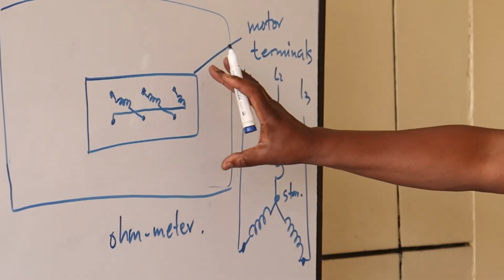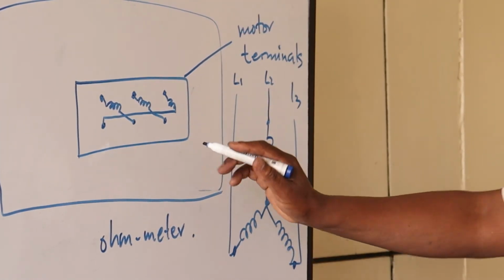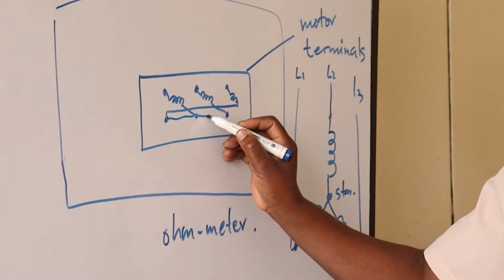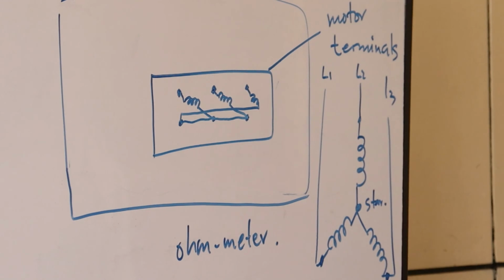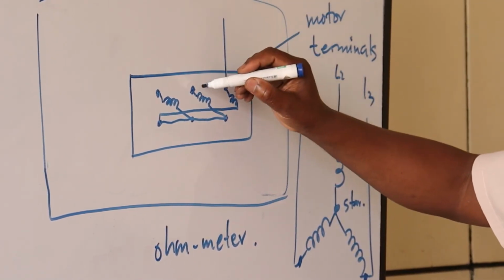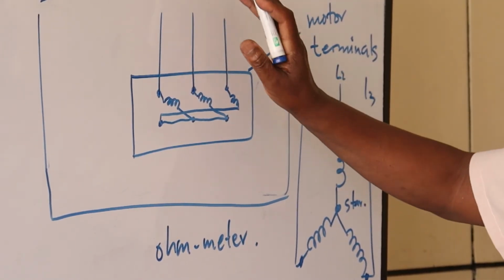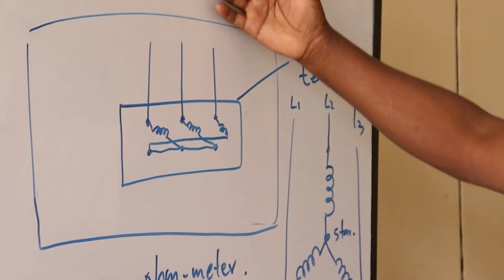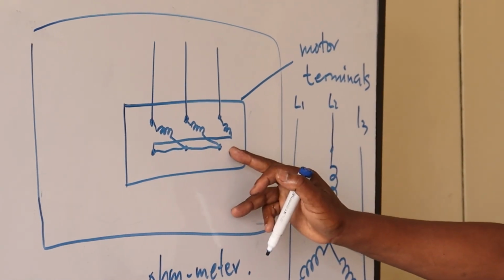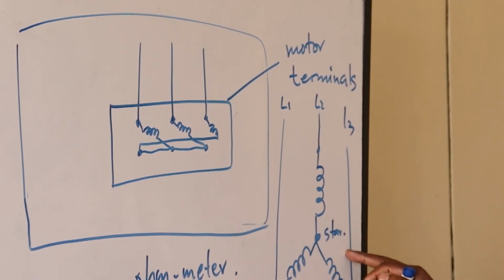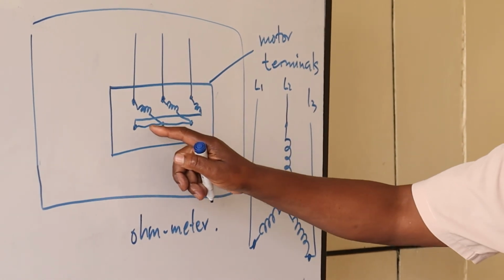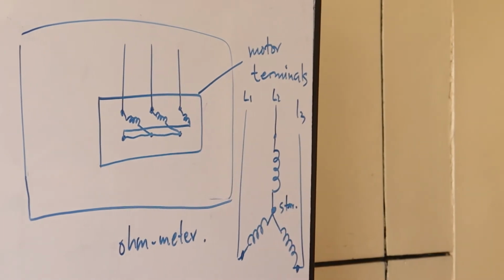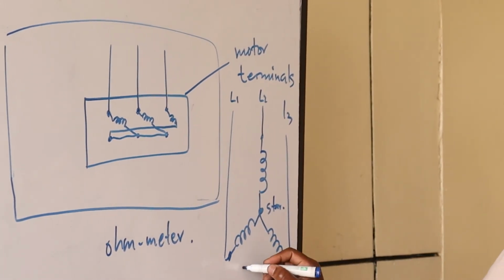So if I want a star connection of these, I can simply short the lower terminals. Physically on the terminals, you put a piece of wire like that, and then your power cables, 3-phase cables, will come like that, going to the starter. So that connection will be star connection. The endpoints are the ones which I've connected together, and the other ends are the ones which I've connected to the power. Now this is for the star.